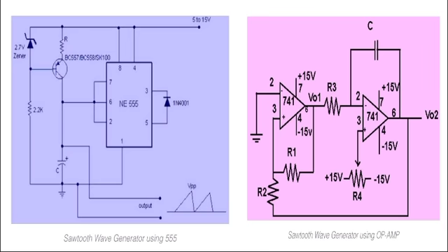When the comparator output goes to negative saturation, the negative voltage is added to the inverting terminal, so the wiper moves to the negative supply. This causes a decrease in the potential difference across R1. So the current through the capacitor and the resistor will decrease.